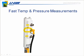So you might be asking, why are these important features? What are the benefits of having this? Well, first, it allows you to capture some of the variables for the WPL term. I'll talk a little bit more on this later in the presentation. Some of these variables are necessary for applying the WPL term. Secondly, it allows for the conversion of number density, which is in milligrams per meter cubed, into molar fraction if you wanted to have micromoles per mole or even ppm.